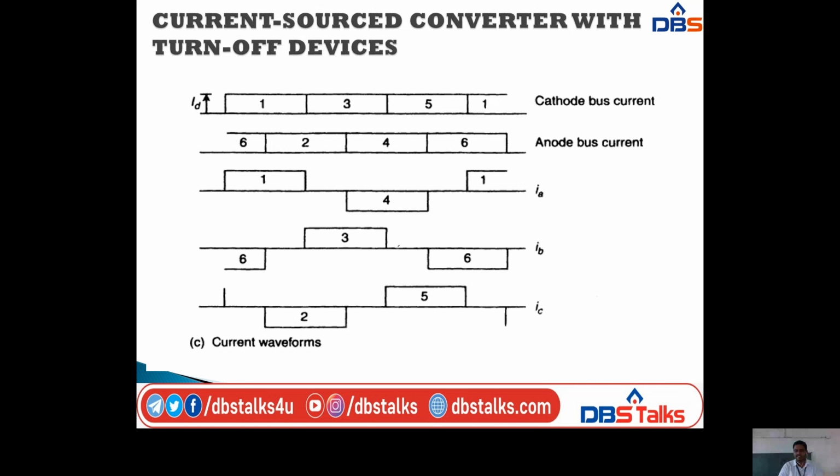So these valves for the A phase, for the current in the A phase we have to use the 1 and 4 devices, and for the B phase we have 6 devices, valves, and 2 and 5 for the C phase. Okay. Waveforms for this concept, current source converter with turn off devices.